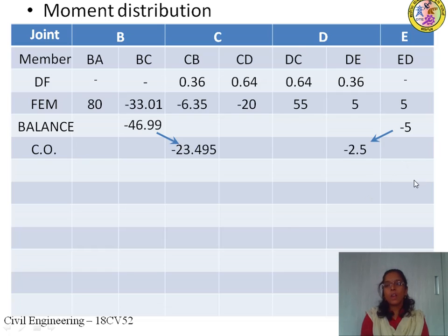Okay, so now at this junction we will make a total. Total at an intermediate junction will be made only in the cases of continuous beams with simple ends or overhanging portions. In this given problem we have the combination of both, therefore we are having a total at this junction.